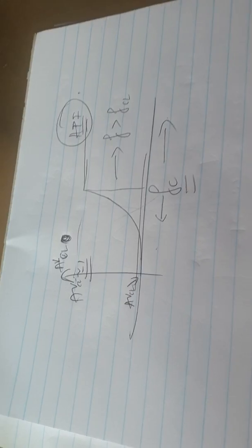It passes higher frequencies. Both these filters are active because, as you learn in other subjects later on, there's a way to design a filter that will do exactly the same, but with passive components, meaning without any component that needs to be powered to perform its job. In this specific case, it's an active high pass and active low pass filter because they both use operational amplifiers that need to be powered. They need 1 or 2 active voltage sources: 1 in the case of single power supply, and 2 in the case of split power supply.